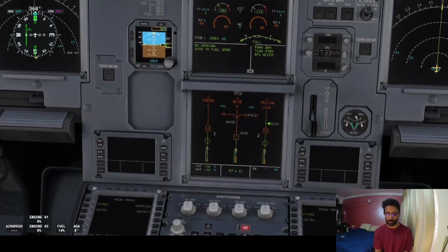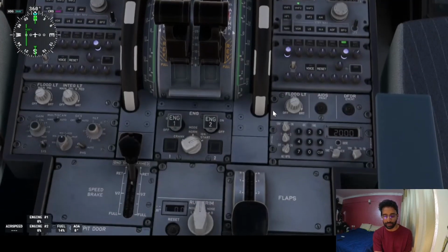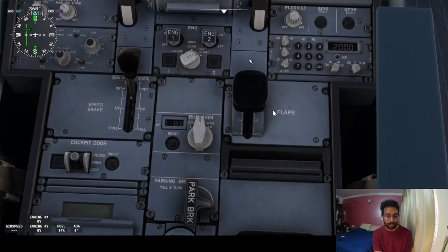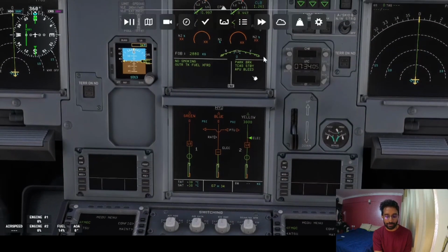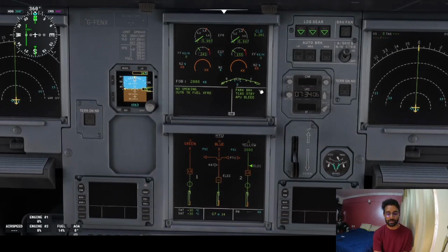Now let's turn on the cargo door. See, when the cargo doors are operating, remember the electric pump pressurizes only the yellow system now. PTO is inhibited at that time. Now you try to put the flaps to 0. What happens? Say some guy is standing holding the flap. You don't know, right? These guys, they're not trained like us. So if that happens, what happens?